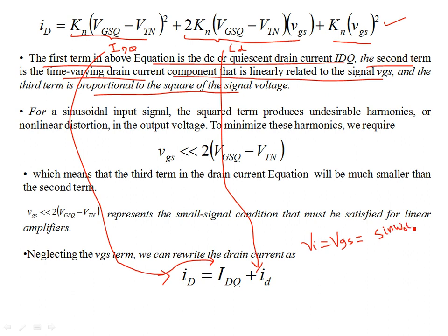Amplitude is not important, but what happens if you square this? When you square this, then you're asking for harmonics, right? I mean, sine square omega t, if you recall the identity, cosine twice omega naught t is 1 minus twice sine square omega naught t. Which means that you can express your sine square term in terms of cosine 2 omega naught t.